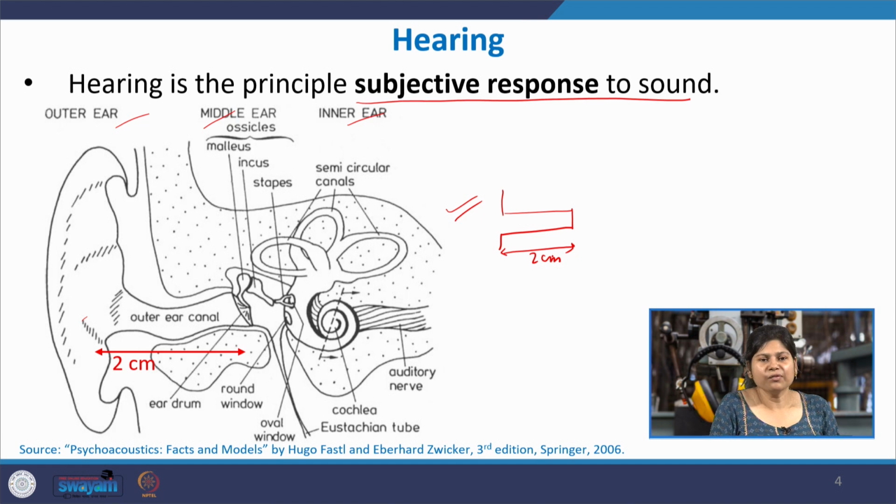Whenever sound waves are flowing in a tube and suddenly there is a rigid closed boundary, the particles cannot flow through. In that case the particle velocity at this end becomes 0, which means that del p by del x, to which the velocity is directly proportional, becomes 0.